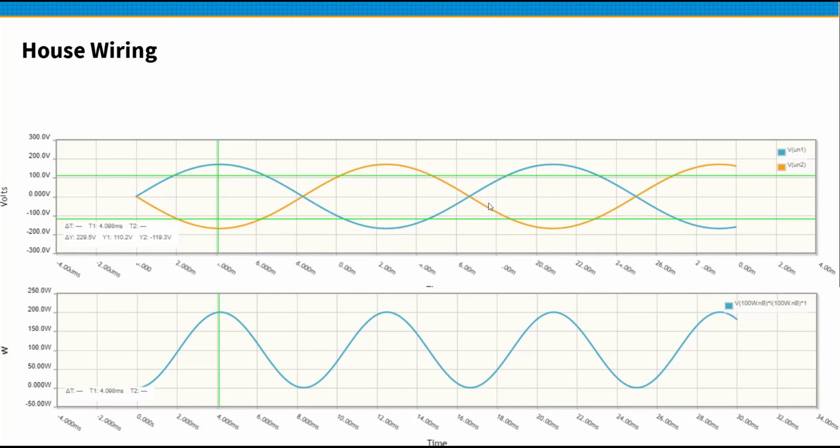Oh, I think someone told me that around here we run, what is it, 120 degree 3-phase. Yeah, but this is not 3-phase. This is sort of, nobody calls it 2-phase, but with the neutral, it's actually 2 phases that are 180 degrees apart. Whereas your 3-phase, you're 120 degrees. And if you were 4-phase, you'd be 90 degrees. You don't see much of the other phases, but most power stuff, big motors, power transmission is 3-phase.